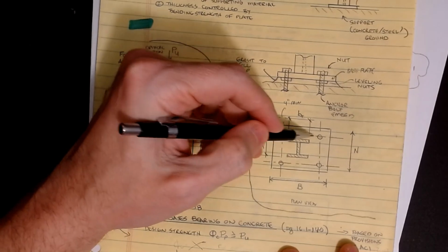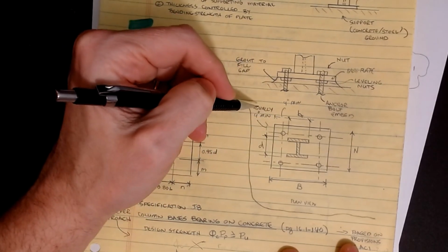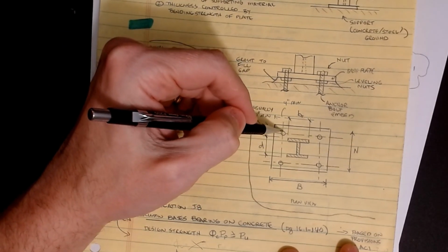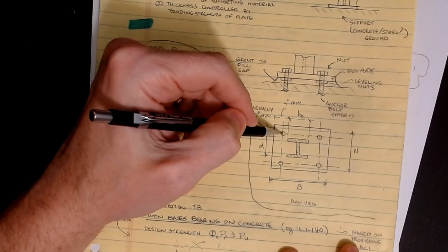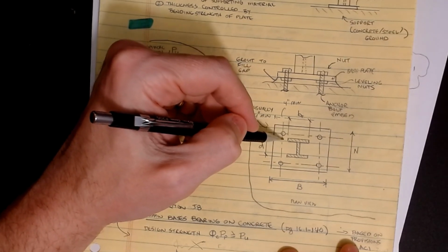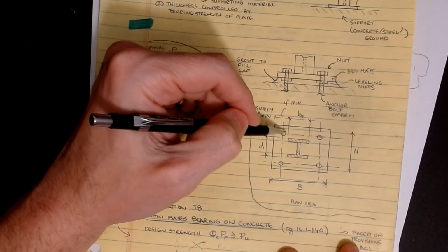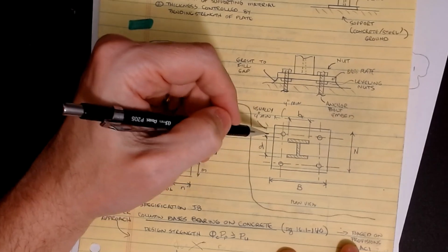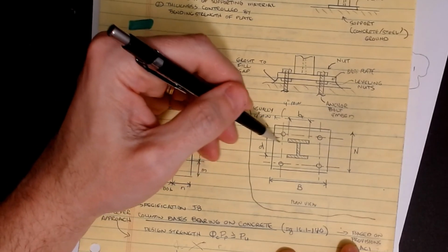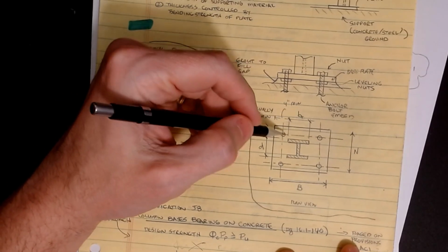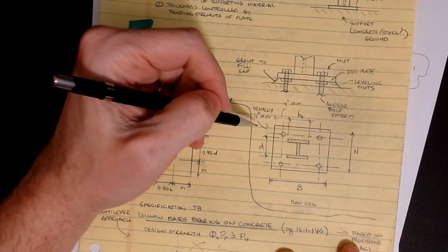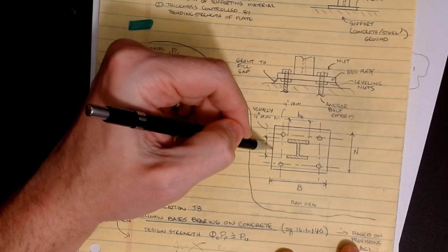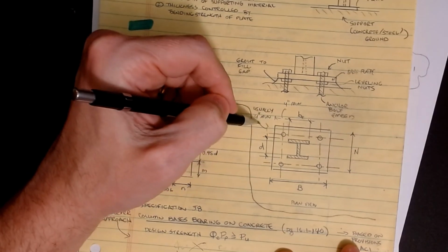Now, there are some other design considerations we have to look at. In order to accommodate anchor bolts that are outside of the web, normally you need something like 2 inches from the edge in order to physically provide enough room for the hole and a washer and a nut to land on top of it and still be in full bearing on the plate. So normally one way that you can get a quick size guesstimate for this plate is to take the depth of the beam and then add basically 4 inches on this side and 4 inches on this side. That gives you plenty of room to get the hole in.